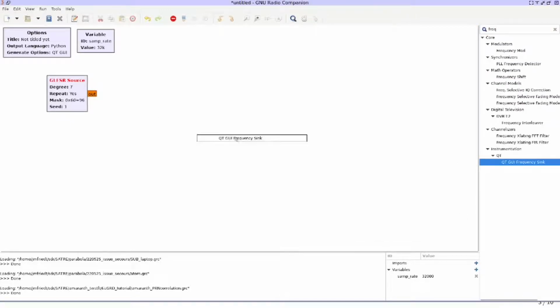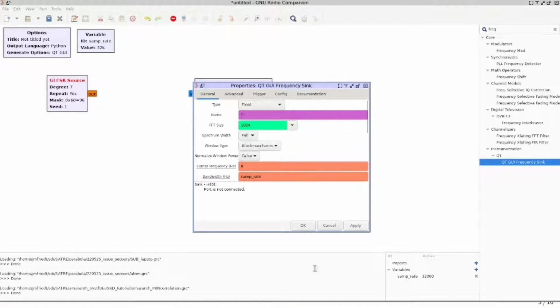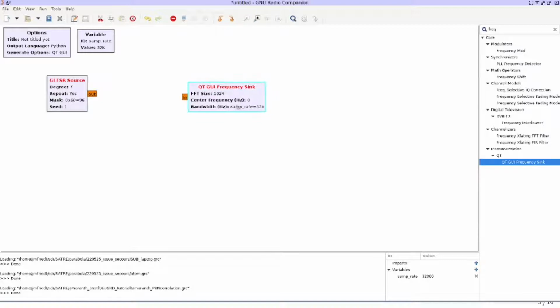So if there is some repeated pattern, we'll have some spectral component. If we have truly noise, then we should have a flat spectrum, because the Fourier transform of noise will be a flat spectrum. All frequency contributions are equal.